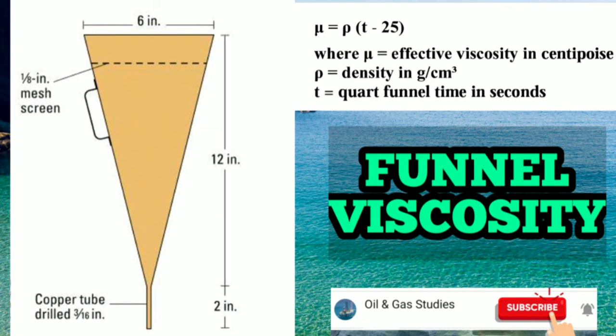The Marsh funnel is a simple device used for the routine monitoring of the viscosity, and should be performed alongside the mud weight check. Marsh funnel readings are affected by mud weight, solids content and temperature. The value from the Marsh funnel should only be used for comparison purposes and for monitoring trends. The following figure is given for Marsh funnel.